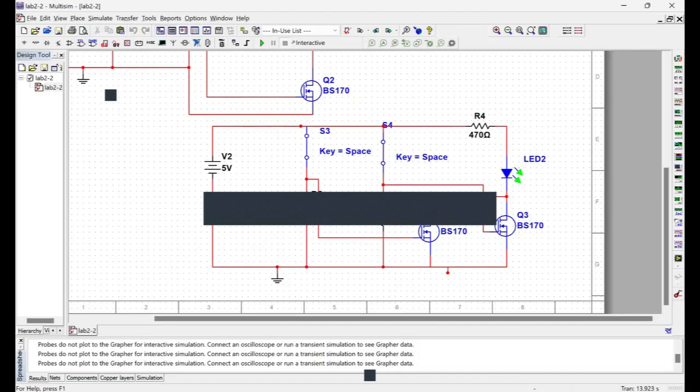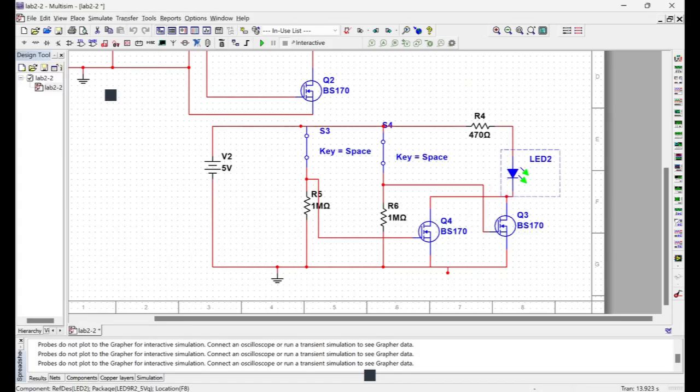Now, we just disconnect the LED from the circuit, put it here. Now, the resistor is directly connected to the logic block, and our LED is connected between the point between the logic and resistor, and the other side is ground.